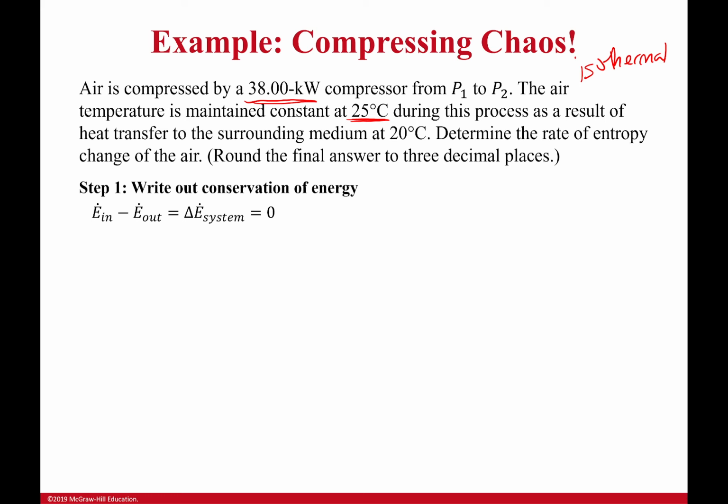Now, some details here help me realize a few things. First off, this part is usually connected to some sort of change in temperature for your medium, your working fluid. And it tells us that that's maintained constant. If it's constant, it's going to be equal to 0. So we know that my change in energy with time of my system is 0, so I can just say that my energy input is equal to my energy output.